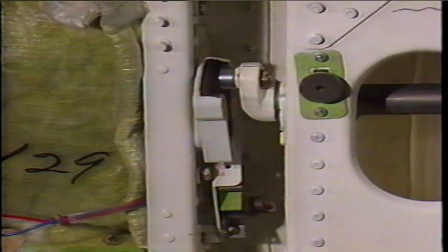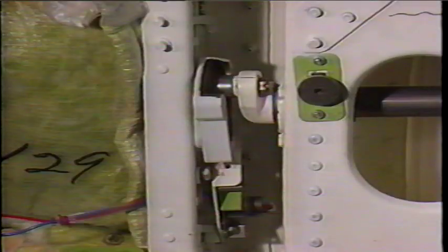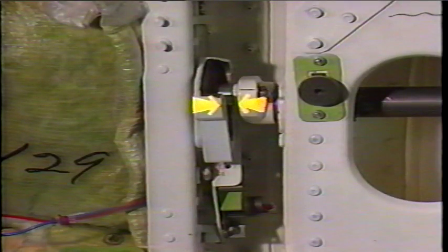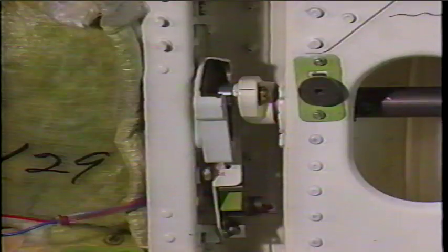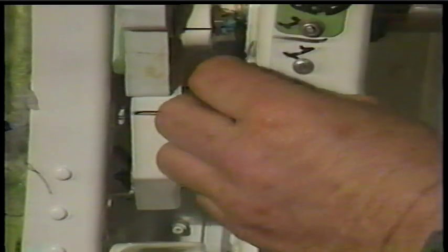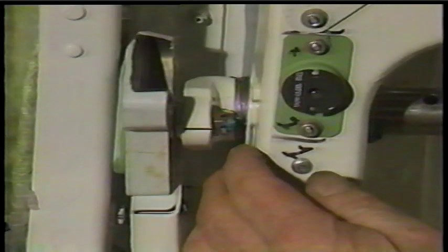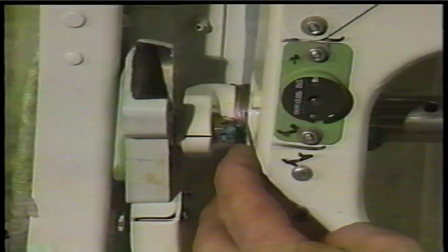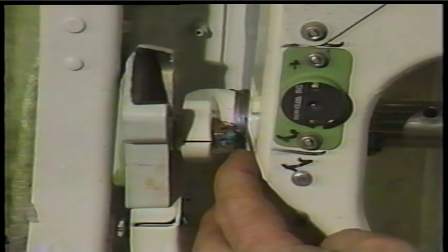Close the door. Check the fore and aft position of the latch torque tube by measuring the X gap between the face of the latch crank and the face of the body-mounted latch cam. These gaps should be equal within tolerance. Adjust the gaps as required by exchanging spacers between the forward and aft ends of the latch torque tube. One spacer thickness is equal to 24/1000ths of an inch.